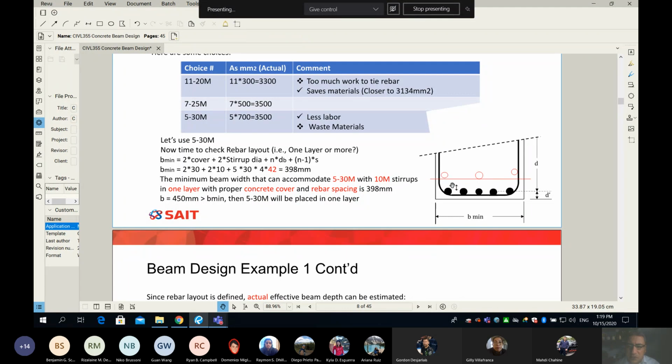And some put these ties, because this also keeps the width of your beam constant. You're pouring a lot of concrete, and especially if you have a very deep beam, you have lots of pressure at the very bottom. So this tie here will keep the width of your beam.